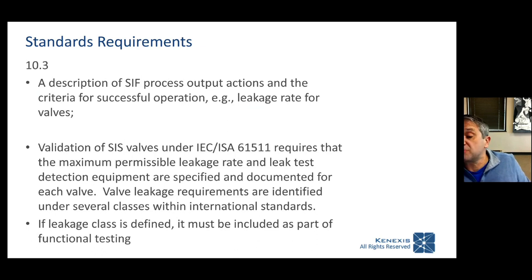Okay, well, what did you just buy? When you specify something, we're going to get to the safety life cycle segment called validation. So validation is coming. And when we get to the validation phase, part of the validation process is going to be checking every SIS instrument and ensuring that that instrument meets the requirements that were specified.